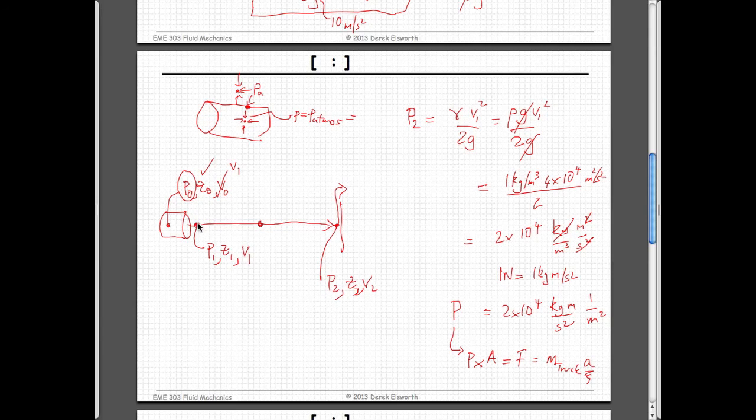If you choose to write it just outside here, for the rationale we gave, as soon as it enters the air, as soon as it comes around this lip, roughly, it won't be exactly, but it should be equal to the atmospheric pressure, because fluid pressures at a point are equal in all directions, and they have to be atmospheric pressure outside this stream. So as you go normal to this stream, you can argue it should also be atmospheric pressure inside this stream. You know this, you know the elevation, and you can estimate the velocity.